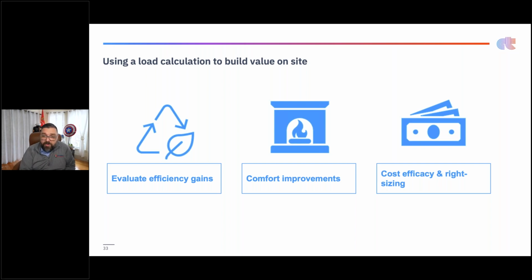Don't just do it for free and give the homeowner the size to go shop around, right? Make sure it's part of your process and doing it right, so that way you can sell the right size system to begin with. And everybody has a different way of doing it. I know a lot of the local guys I've taught will tend to do a block load first, sell the system, and then go back and do room by room with the software and spend the time after they know it's won. Time well invested, right?